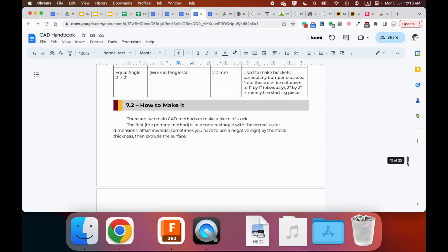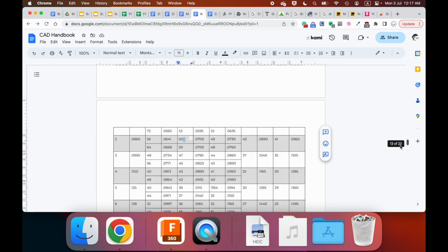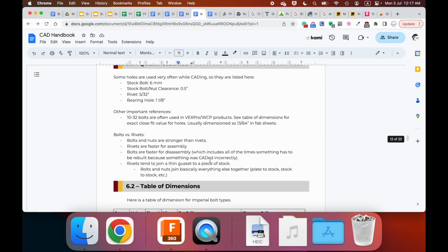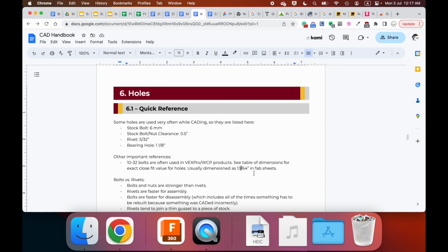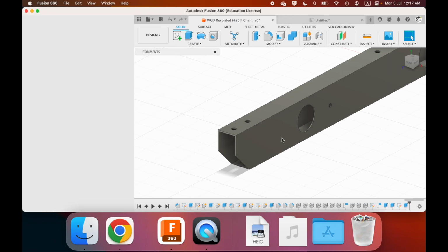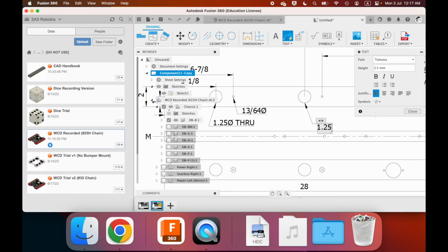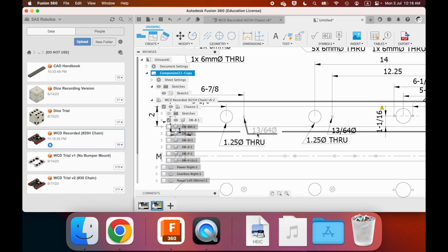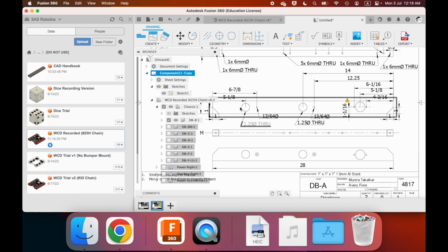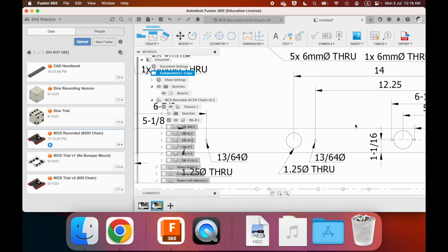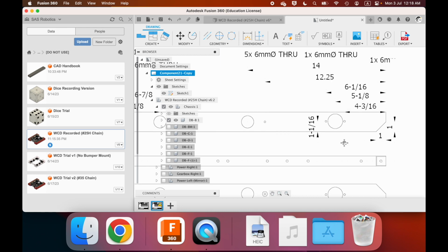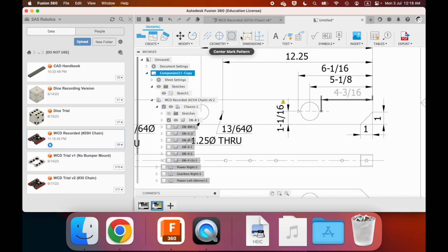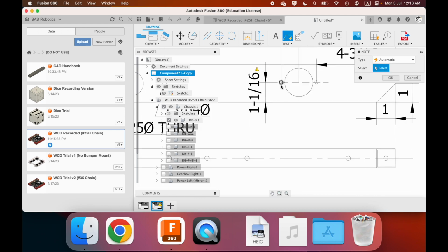That's strange. So I know this is for the cam, which is a 1032 hole. Okay, well anyways, this is in quick reference, so we'll just label it as a 1364. So just to be clear here, drill bits have all sorts of different sizes. The drill hole size can be divisible by a 64th, but the hole position should be at most divisible by a 16th, or like over 16, if you know what I mean. It shouldn't be a 32 fraction.